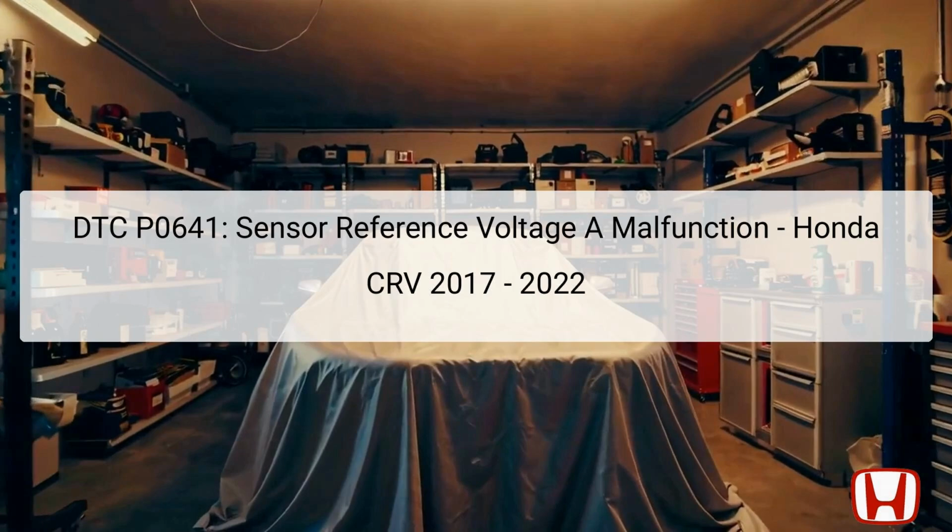The diagnostic trouble code, DTC P0641, signifies that there is a malfunction in the sensor reference voltage A circuit, which is crucial for various components to function properly. This code indicates that the engine control unit, ECU, is not receiving the correct voltage levels from the sensors it utilizes for operation. The affected components generally include the manifold absolute pressure (MAP) sensor, the fuel rail pressure sensor, the